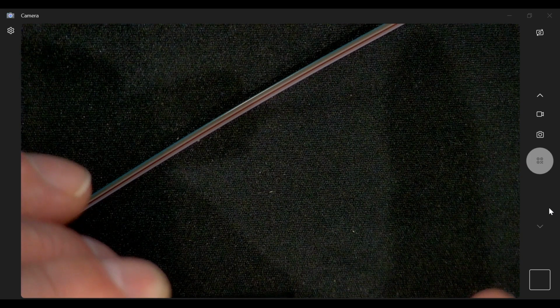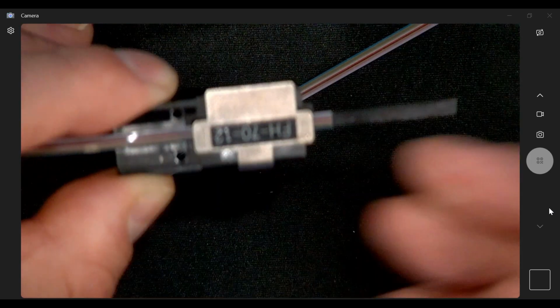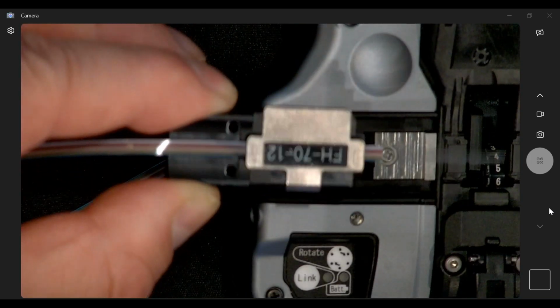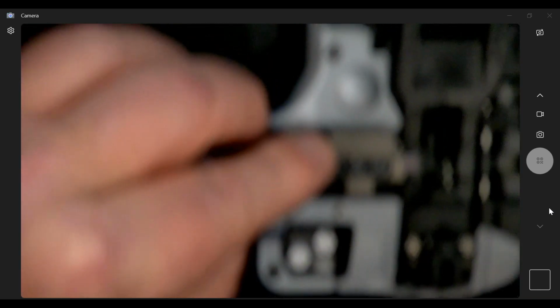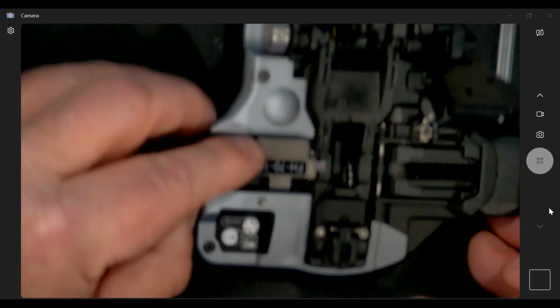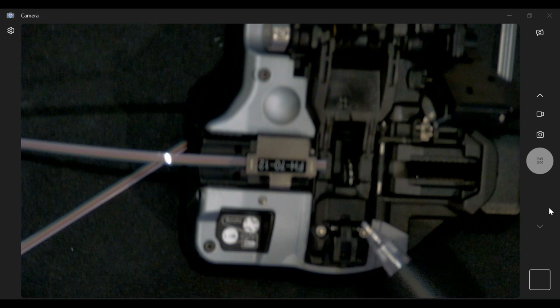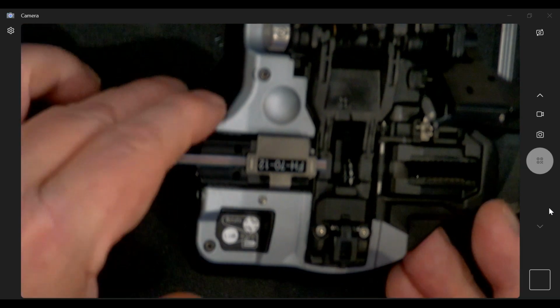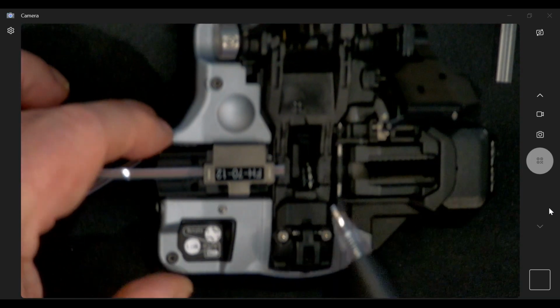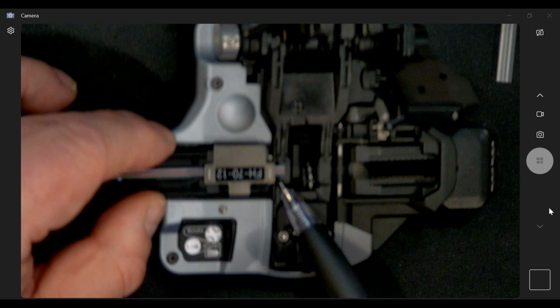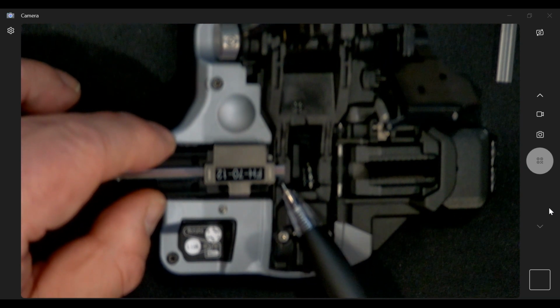But the reason I want to pull this out is that I move this to the CT50 cleaver. You will actually see a negative here. As a result of that fiber holder slightly slipping, you will notice here the coating has come up on top of the pad, the elastomer pad of the CT50 cleaver.